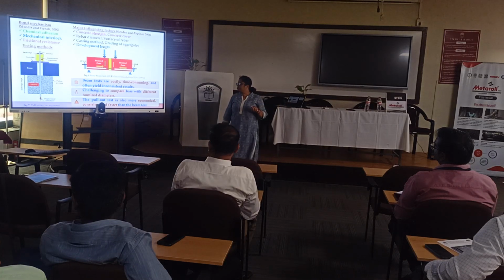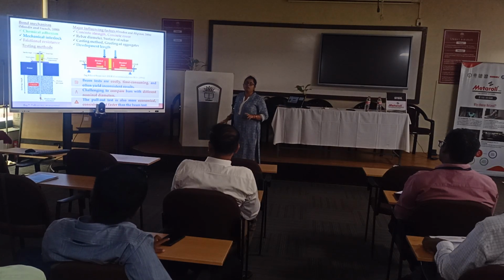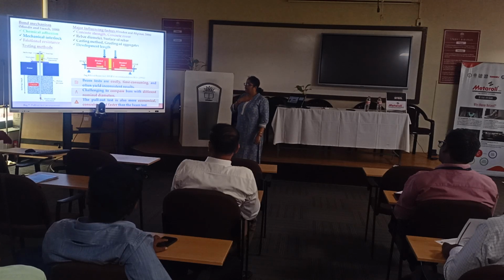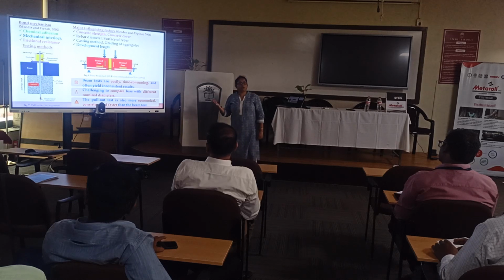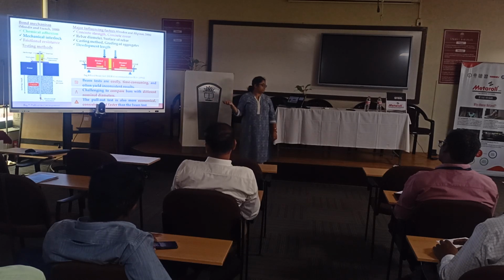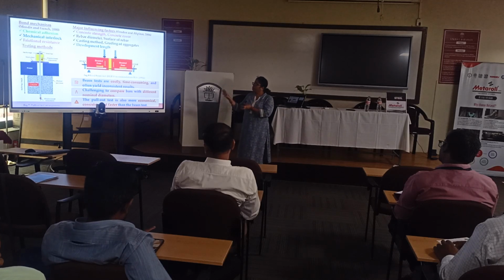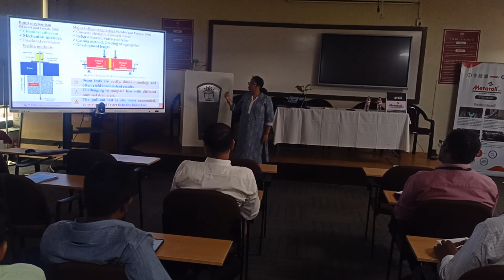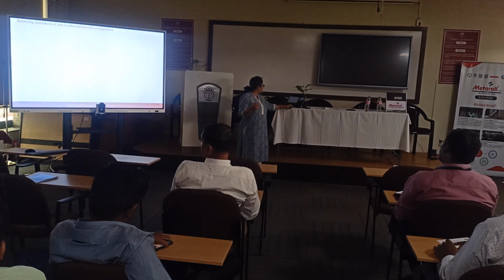So why did we do this monitoring first of all? Because normal beam bending testing and pull-out testing are destructive in nature, time consuming, and need lab hours. It is also not very economical, because you destroy the specimen in tension, or you take a core out of it and do some testing, which is not good enough to make repetitive. So we should do a bit of SHM on this part.